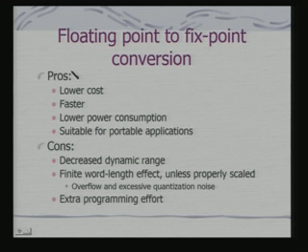So, the next part is the floating point to fixed point conversion. What is a floating point representation? You have a mantissa and you have an exponent. Depending on the value of the exponent, you can have variable precision. When you have a fixed point, that is not there. You have a fixed number of digits allocated for your fractional part.